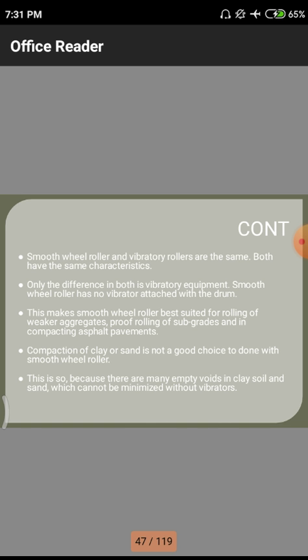In clay soils and sandy soils the variation in particle size is very high, because in sandy soils the particle sizes are 0.05 to 10 millimeters, but in clay soils we have 0.002 to 0.005 millimeters. So the particle size varies a lot, so we don't use these vibratory and plain surface rollers for those. We use plain and vibratory rollers only for aggregate-like surfaces.